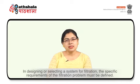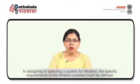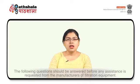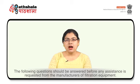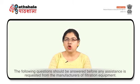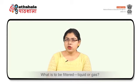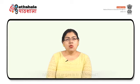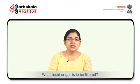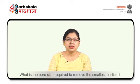Lastly, we will discuss how to select a filter. In designing or selecting a system for filtration, the specific requirements of the filtration problem must be defined. The following questions should be answered before any assistance is requested from the manufacturers of filtration equipment. First, what is to be filtered, liquid or gas? What liquid or gas is to be filtered? What is the pore size required to remove the smallest particle?